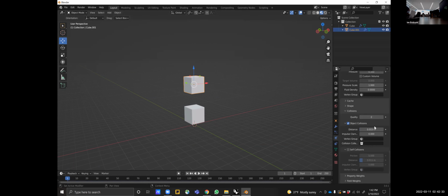You can change the quality of the simulation, but also the distance offset from a given surface that things will hit each other from, like a kind of force field. If you find that things are flipping through each other, we want to just increase that distance. So we put it at 0.5 meters and 0.5 meters. They'll be more afraid of hitting each other. Oh, you see, they have a force field between them.